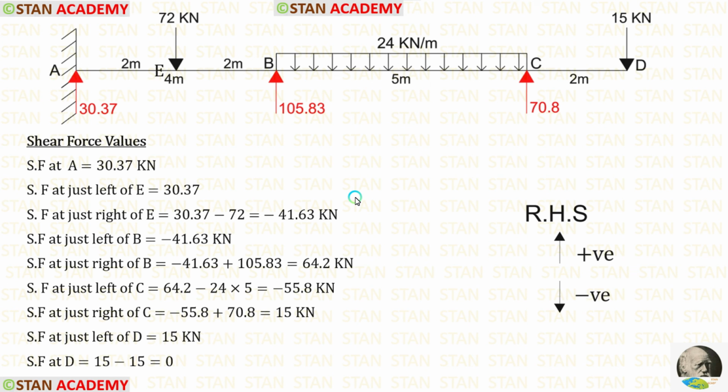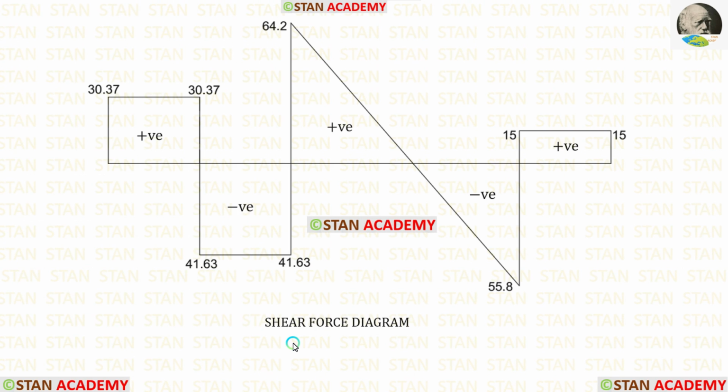Now we are going to make the shear force diagram. Before drawing the diagram, let us calculate the shear force values. I am moving towards right hand side. Upwards will be positive and downwards will be negative. Using the values, we can draw the shear force diagram.